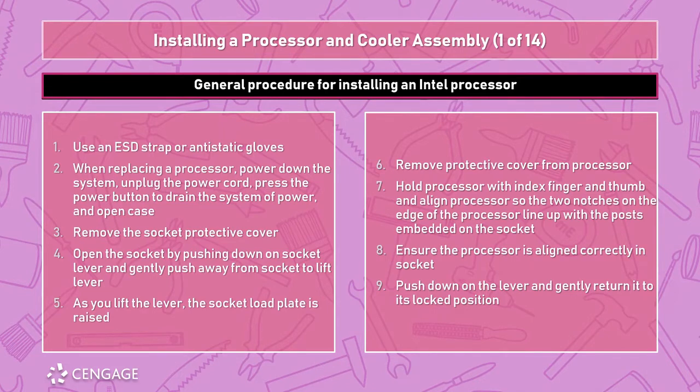The socket, if it's a new motherboard, will have a protective cover. Go ahead and pull that off. Open up the socket by pushing down on the lever and lift away using the lever, the socket leveler. So you're going to press down, away, and then let it lift up, and you'll push it backwards to open the plate. The load plate is just a metal, it's not quite a ring, it's a square or rectangular frame that covers the edges of the CPU to hold it in place evenly. It's what we call a zero insertion force socket.